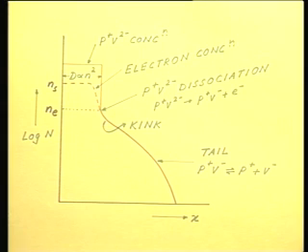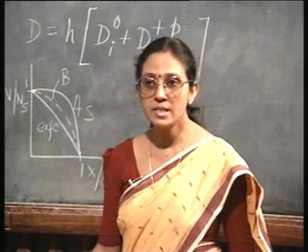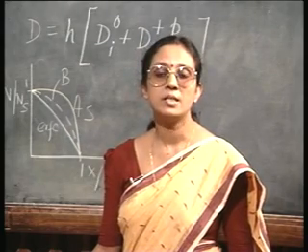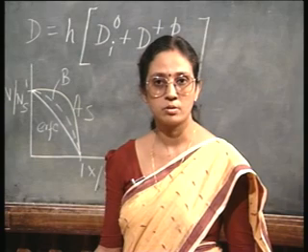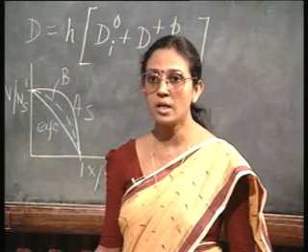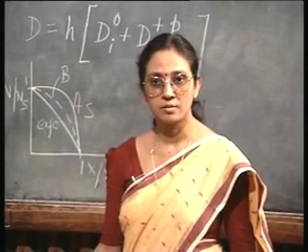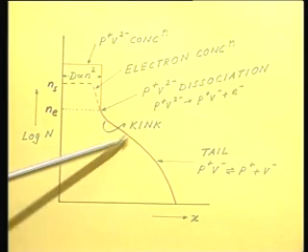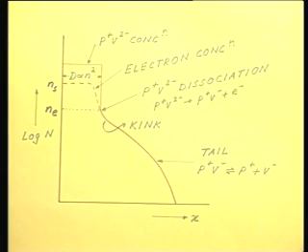So, it dissociates more easily, and in the process we have a lot of vacancies. Now, because of these vacancies, there is an enhanced diffusion. You know, diffusion is going to be primarily dependent on the availability of the vacancies. So, in the tail region a number of vacancies are created because of the dissociation. So, the diffusion gets enhanced, that is why you have an extended tail into the bulk material.